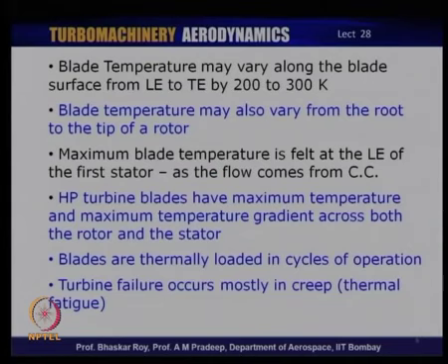So, as we were saying, the blade temperature also may vary from root to the tip of a rotor. Stators, by design, as we have seen, may be kept untwisted, but the rotor may have a little bit of twist, and that will give rise to temperature gradient from root to tip. So, that again needs to be factored into this very accurate cooling technology that we need to incorporate in modern axial flow turbines.